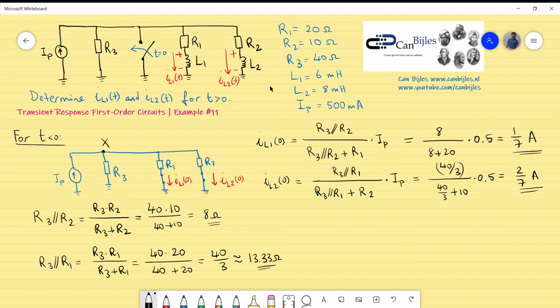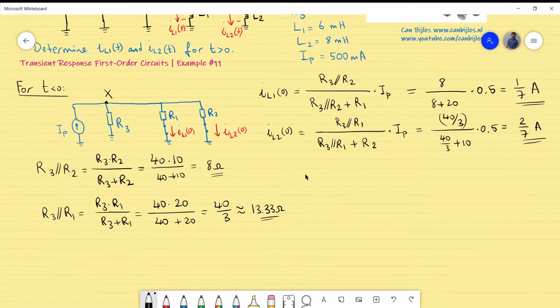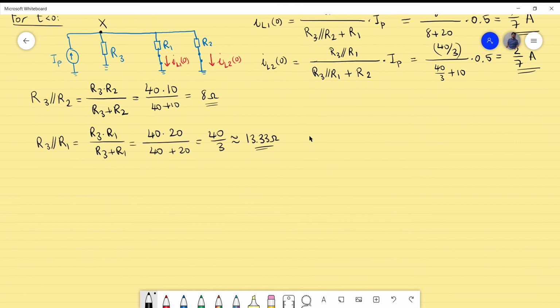So that will also be the final value of the currents through the inductors will therefore be 0, because they will lose all of their energy. There is no other way to sustain the energy. So that's actually very interesting to note here. Because there is no other independent source left, the energy stored from the first condition will be dissipated completely in this second condition. So I will draw this situation.